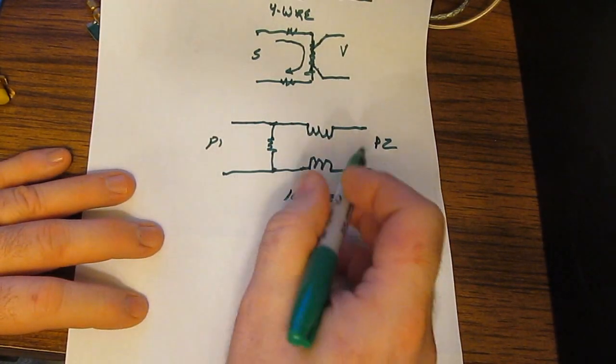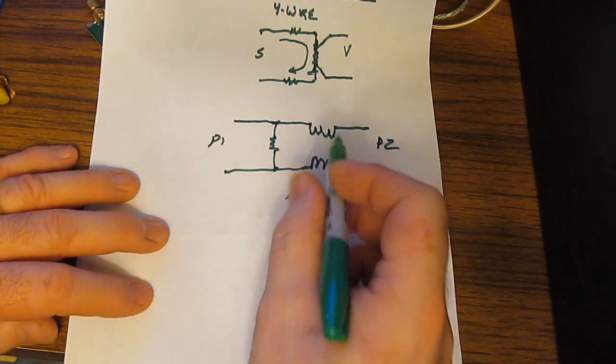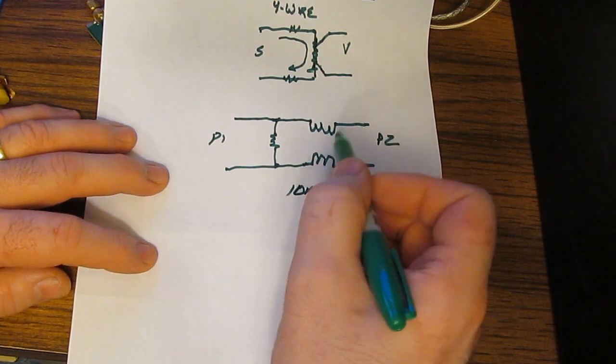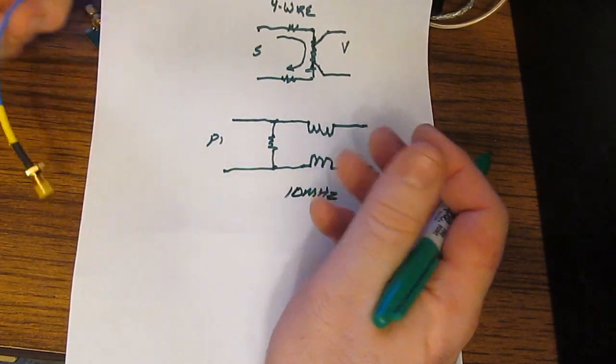I demonstrated that when I was looking at some very low ESR, high Q RF parts from American Technical Ceramics in a video a while ago. Basically, I didn't have to deal with the common modes because the coax cable itself was so lossy.